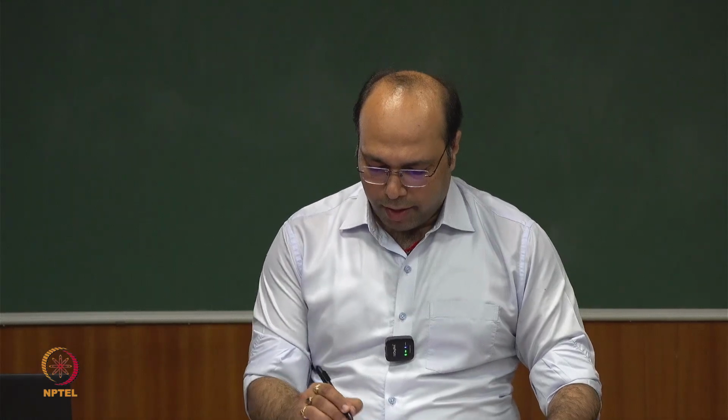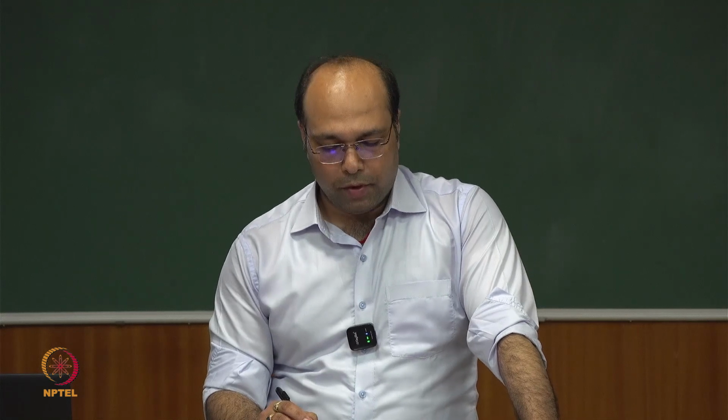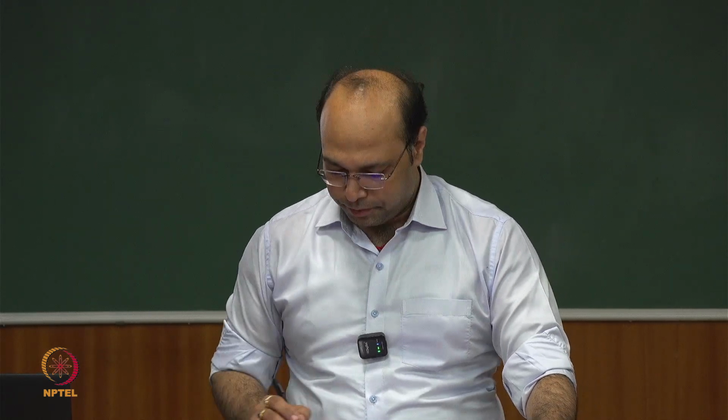Now some understanding must be developed at this point of time: when we are talking about the direct axis, or flux axis, the orthogonal axis is called the voltage axis. However, our voltages are not directly aligned along the Q axis because of the IR drop and other factors. So we have our voltage vector a little bit shifted from the Q axis. There is a certain angle formed with respect to the Q axis, and this is coming on account of the loading and other factors, resistance and loading, etc.